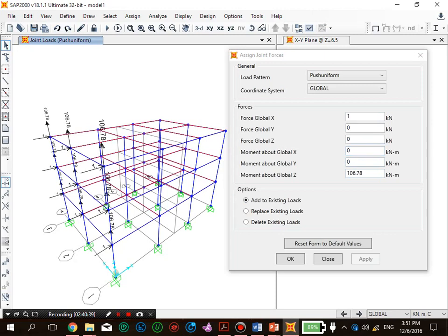Here, guys, before I click, I forgot that there is a moment. How to solve that? You repeat that, you put 0, and then you put replace. In this way, you can remove the moment that I generated by mistake. Because there was a value here, and I forgot to remove it. The previous selection here is important. Look, the nodes are selected again. Apply, and the moments are gone.